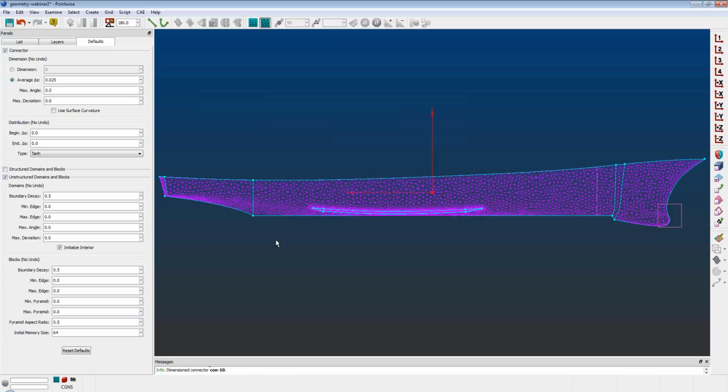Now, the question a couple of questions ago was asking about the anisotropic tetrahedral extrusion. That's specifically what that method addresses. The idea with the TET extrusion method is that instead of using prisms, we use TETs to create layers of high aspect ratio right-angle cells in the boundary layer.